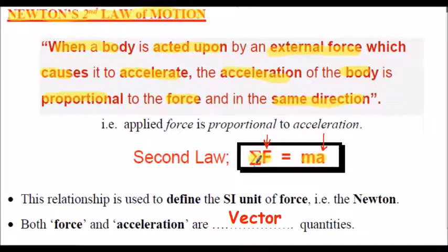Again, I call it the summation of all the forces because there's often more than one force applied to the body, so I'm adding up my forces. But again, we need to be very careful here. We are dealing with forces, so in the SI system we need to use newtons of force, not the kilogram. So make sure in all our calculations our forces are in newtons. And because forces and accelerations are vector quantities, we have to account for their direction. And that's very important.